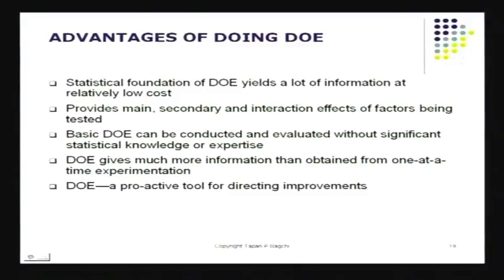In the older experiments, you also had to do something called ANOVA, analysis of variance, to come up with your optimum settings and so on and so forth. Now you don't have to do that. You don't have to really worry too much about significance. If you control the background noise, and if you use a simple enough matrix, you should be able to work out the factor effects and their interaction. That you should be able to do.